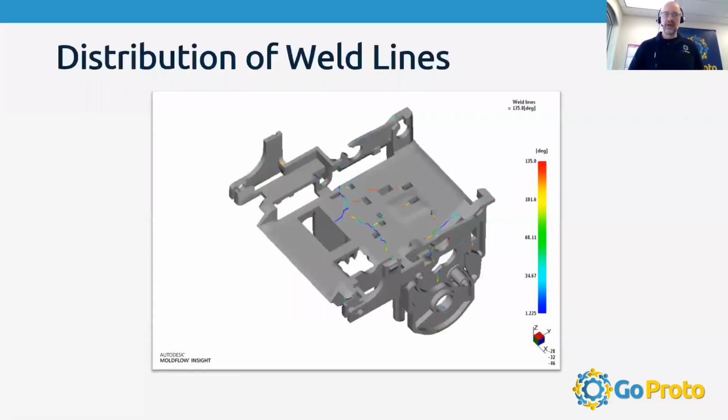Next slide. Then weld lines, these are flow fronts. The material is flowing from those gates that we showed two or three slides ago, and it's flowing out around any obstructions, i.e. holes in this case, and flowing back around like a stone in the river. You know, the water separates around the stone and then comes back together on the backside. Or like hot lava, you consider, and then it's getting cool. And as it comes back together, it needs to knit back together. And you'll always see a knit line around an opening.